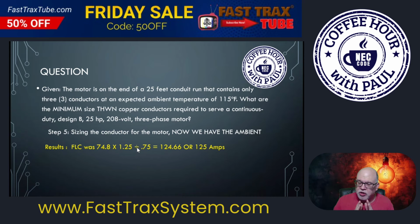So in this case, it's 74.8 amps times 125%. I'm going to do that with you here. 74.8 times 1.25 is 93.5, which we've already done. And I'm going to divide that by 0.75. That gives me 124.66, which we're going to round to 125 for simplicity's sake, because that .66 isn't going to do us much good. All right, so 125 amps.